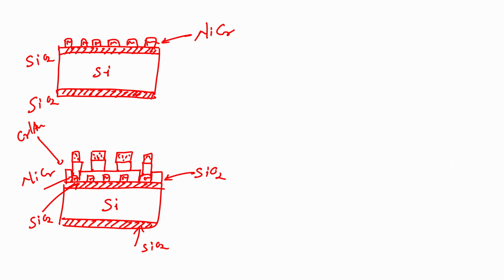All right. So, the area which is protected by photoresist is stronger, and the area which is not protected by photoresist will get etched. After this I will dip the wafer in acetone. Before that, of course, after developing the photoresist we have to do hard bake, do not forget that. So, after this, if I dip the wafer in acetone, I will strip off my photoresist.